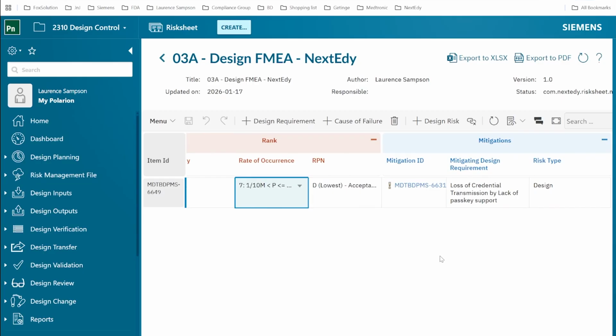Now, we can do this same construction for the process failure mode analysis. And you can imagine we take the physical requirements or the attributes in the design that we've identified as critical to the design performance. We take those and we run them through what part realizes that attribute. We would then identify the process that creates the part, process steps. We'd analyze each process step and we end up with a set of production controls, right? So it's really the same thing. And what this does is it sets up the process failure mode analysis with a characterization of the importance of each physical attribute so that we understand what the implication is. If that attribute isn't met, what's the implication to users as it goes up through this progression?